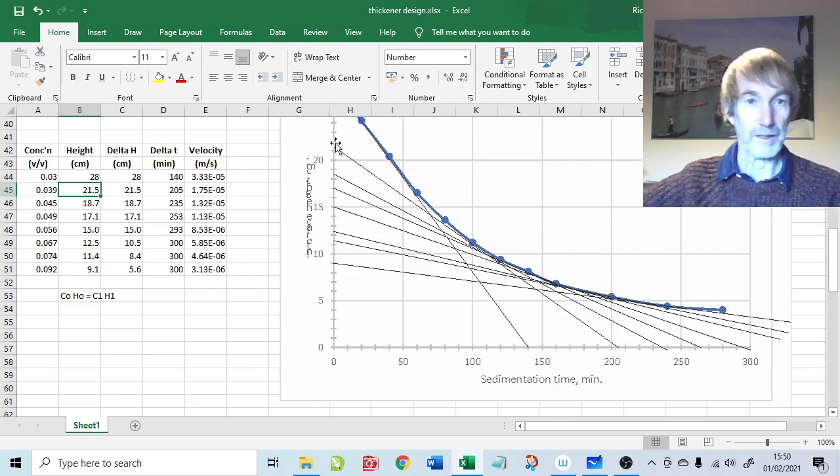Here is the settling curve of a batch measuring cylinder starting at 21.5, and it would settle until it gets to just here, and then it carries on the blue curve. The reason behind that is to do with these characteristics, which were discussed in the previous question, the characteristics which are emanating up from the base.